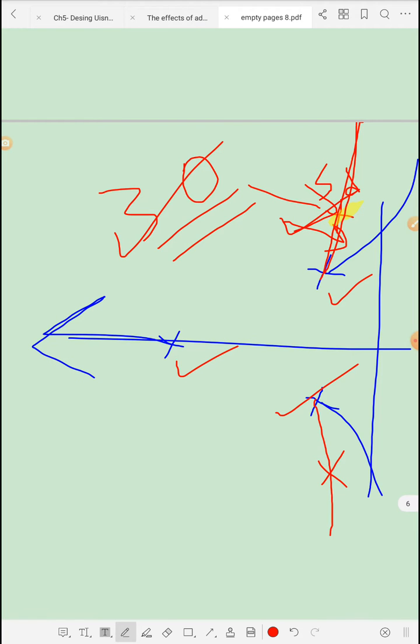If the controller or the compensator provides those 30 degrees, then this means that the new root locus should be passing through the desired closed loop pole location that we have already specified, based on omega n and delta in an indirect way, or based on Mp, the overshoot, and the settling time, if it is from the performance specification of the plant.